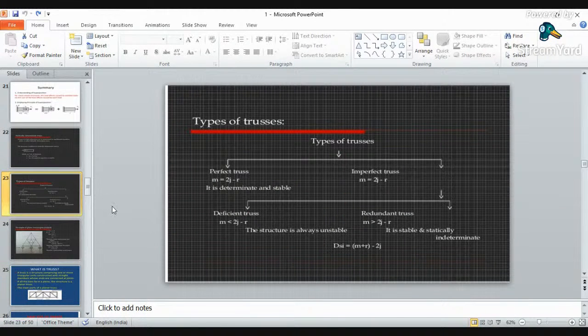One thing let me clear over here. If we say that our structure is either statically determinate or statically indeterminate, that will not actually give the condition for stability, whether your structure is stable or not. Whether it is stable or not is your practical approach. Whether it is determinate or indeterminate is nothing but your structural approach, that is, whether you can analyze this structural component using the equilibrium conditions or not. This is the only condition for determinacy.